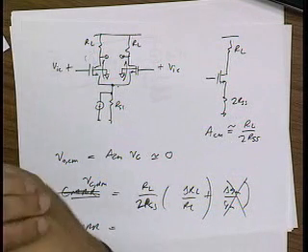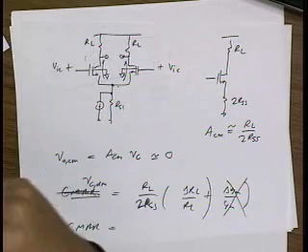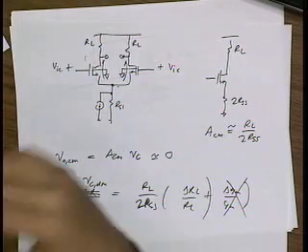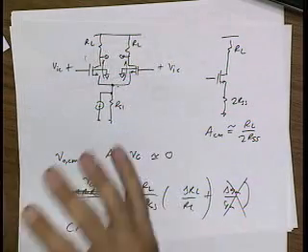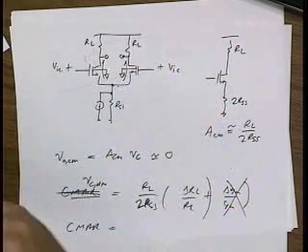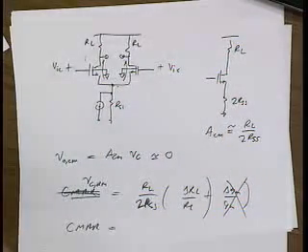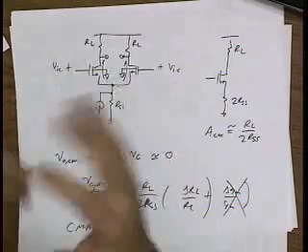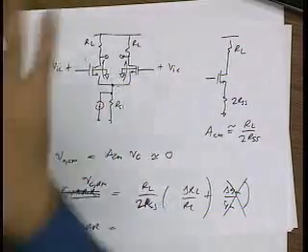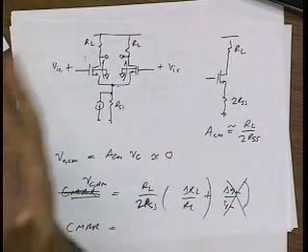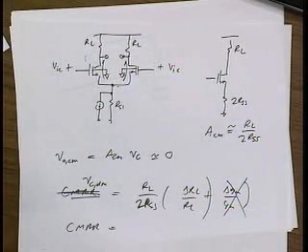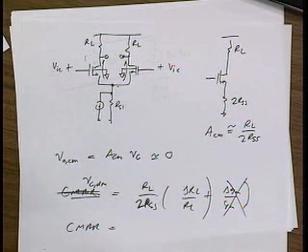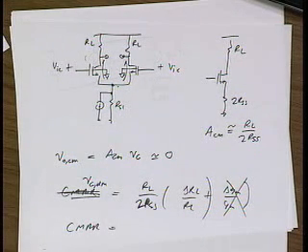What are 2 other good reasons? One is flicker noise. We talked about this before. PMOS devices, being subsurface devices, have better flicker noise performance. So we can get better flicker noise performance if the physics of the transistor makes the current flow under the surface. Unfortunately, that's kind of going away in modern technology, but you'd still see an advantage. Okay, what's another reason? This one you probably don't know unless you've taken a course like this.